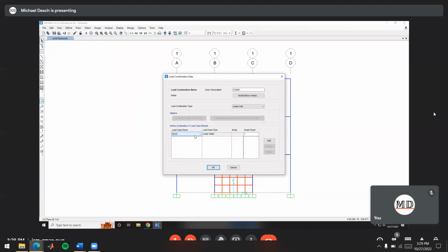Yeah, so these are two of our more prominent gravity load combinations, and you'll use them a lot in steel and concrete design too. Usually 1.4 dead, and then 1.2 dead plus 1.6 live. That's for gravity. We have a little bit of lateral loading in there, so we throw in the 0.5 wind and the other load case we do, which is a more lateral load case.